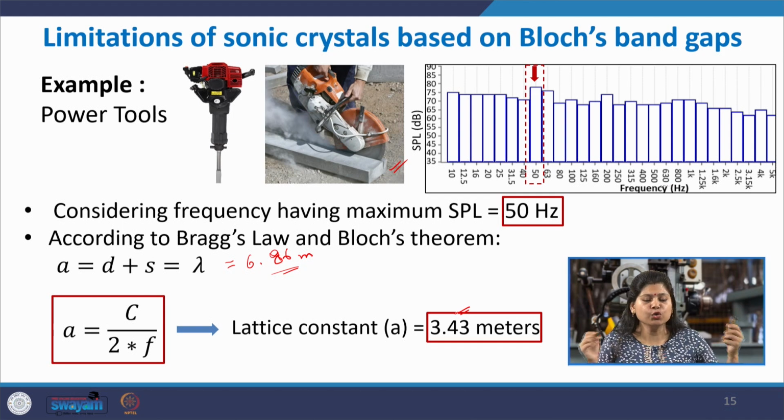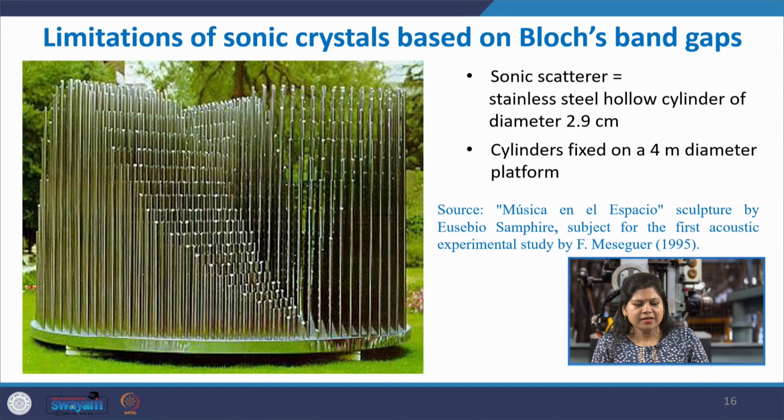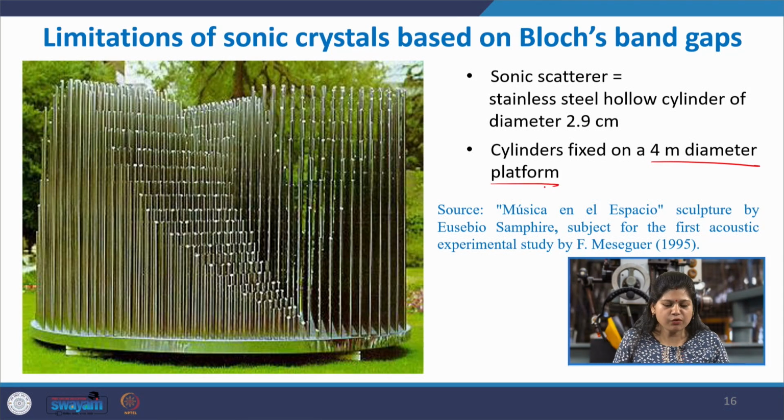Again, a very huge kind of sculpture would have to be built in order to tackle this frequency range, which would be several meters in length. And this shows the example of one such structure. This is one of the very first sonic crystals that was built outdoors to bring down the outdoor noise sources, and overall a 4 meter diameter platform was used.